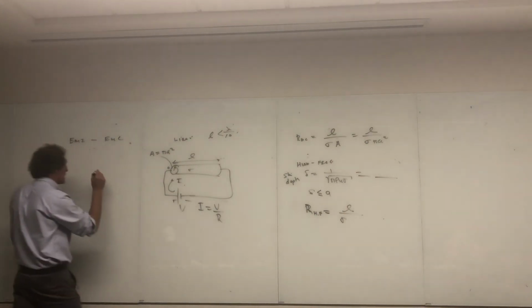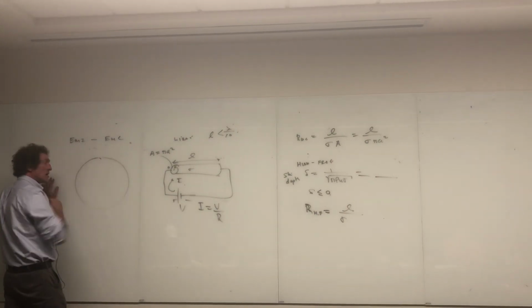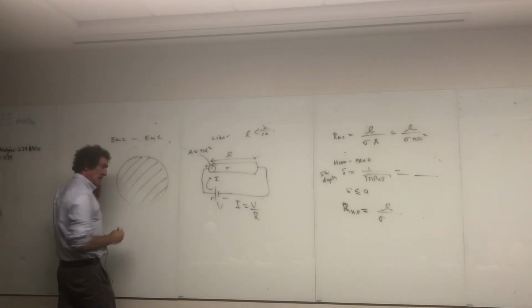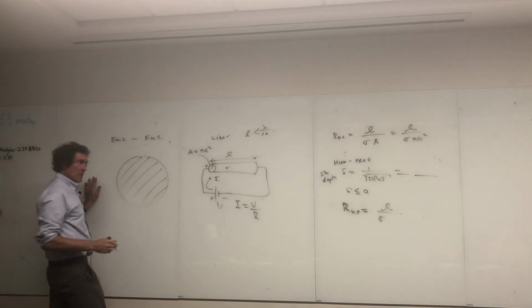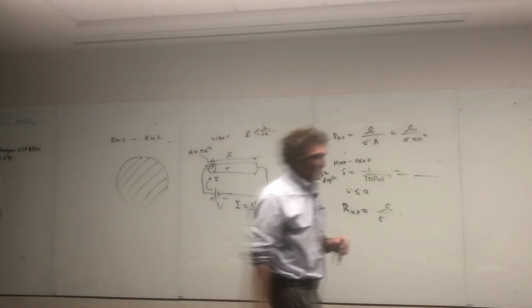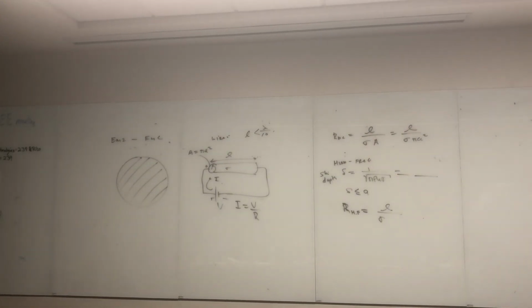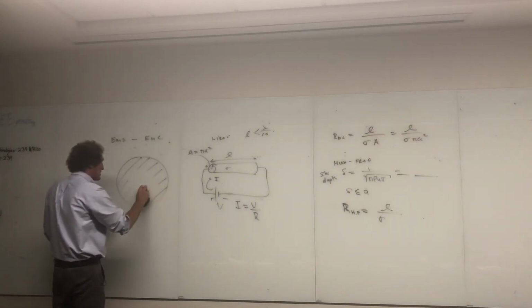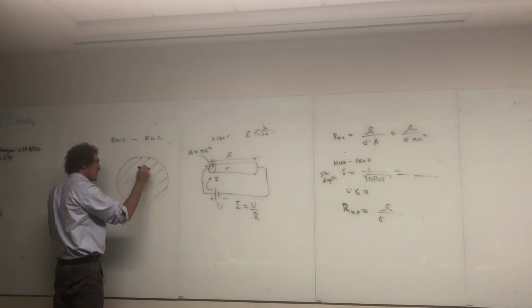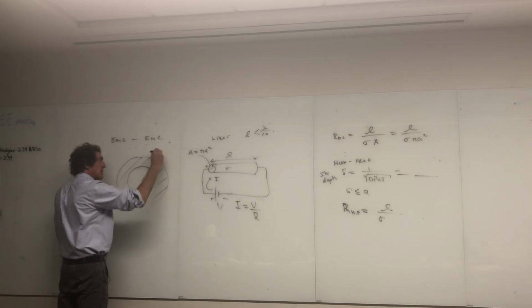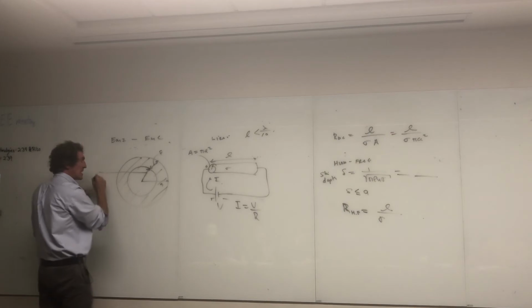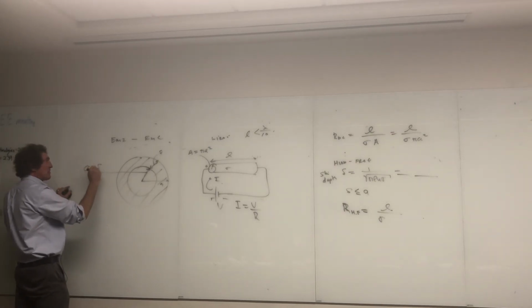If you think of this wire's cross-section, when we have DC current flow, it flows uniformly, ideally, through that entire cross-section, right? But when we have AC current, what actually happens is AC current effectively only penetrates one skin depth. So if we look where the current is, it's all hugging this area here, right? Now this is a skin depth thick right there. And this is out to A, which means this effective radius is A minus delta.